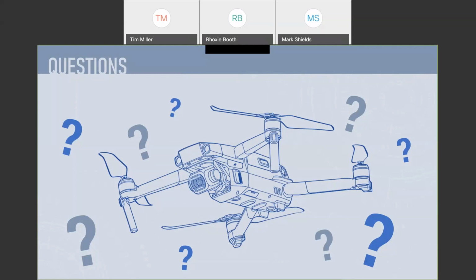Okay. And then what's the battery life for them? Will it capture a full traffic peak hour? Once again, it depends on the hardware. With a tethered drone, absolutely. With battery drones, most of them, I think you get about 45 minutes. Generally what we do is we have 2 pilots on site. So we have 1 drone in the air, and as we get to a point where it's got 10 minutes left, we'll send the other drone in the air, position it approximately where that one is, and bring the other one down. So you usually have 2 video files. Okay, right.